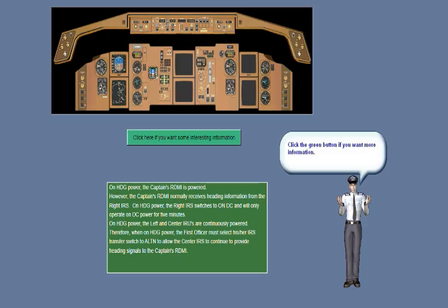Selecting the switch to on, flow bar in view, causes the off light to disappear, APU operating or not. With the control switch on, the APU generator breaker operates automatically according to the priority system.